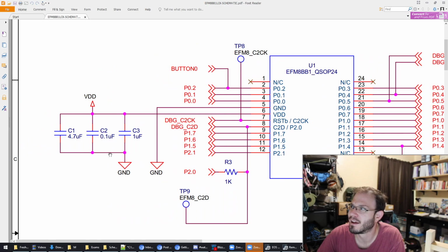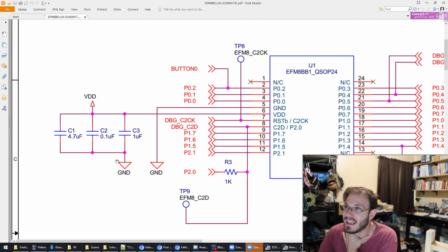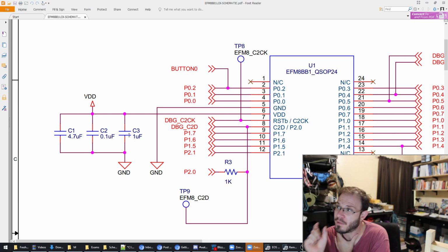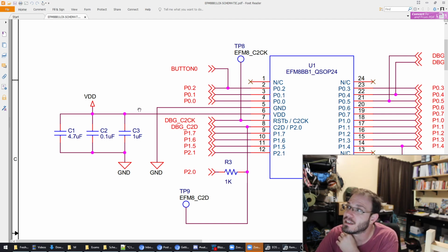Oh, what did I say? Right? They put bypass caps everywhere. Okay? So this is to solve that problem of the parasitic inductance. Mainly, there's other benefits to doing this. Every single design, your digital circuits, you should be adding bypass and decoupling caps.